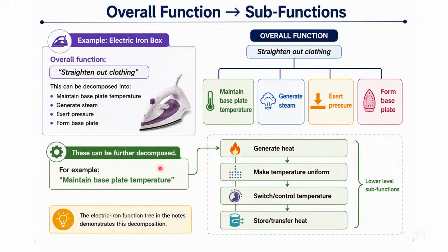Let us take the subfunction, maintain the base plate temperature. How can you do it? You can do it by using these lower level subfunctions, that is generate heat, make the temperature uniform, then switch or control the temperature, and store or transfer the heat. So using these low level functions you can achieve the overall function.